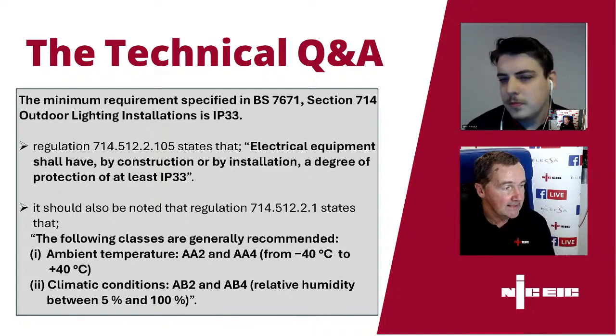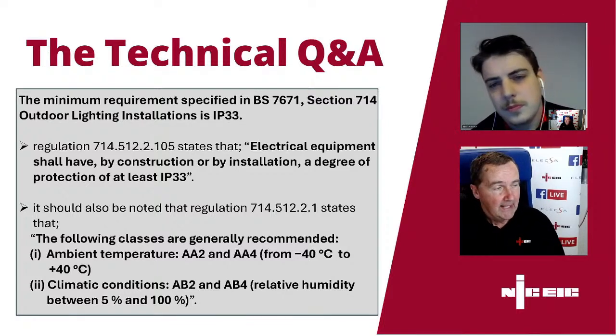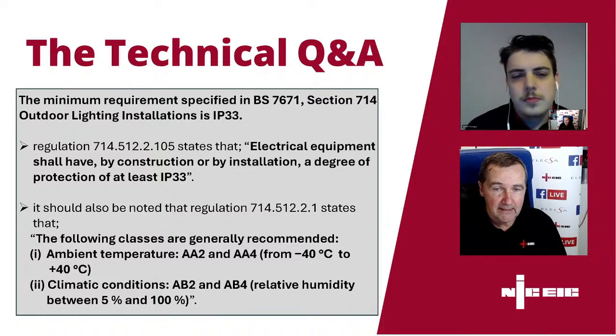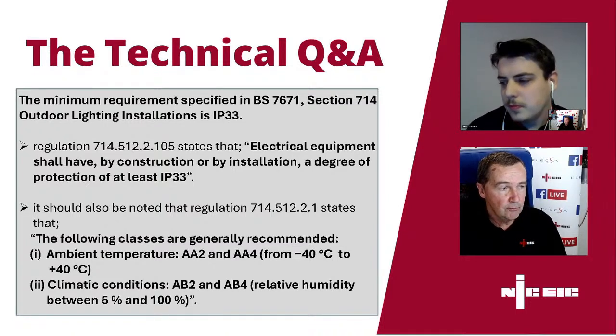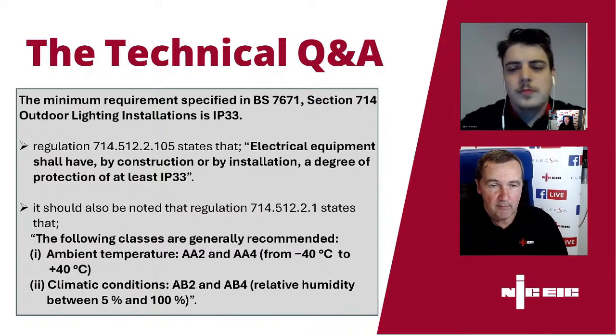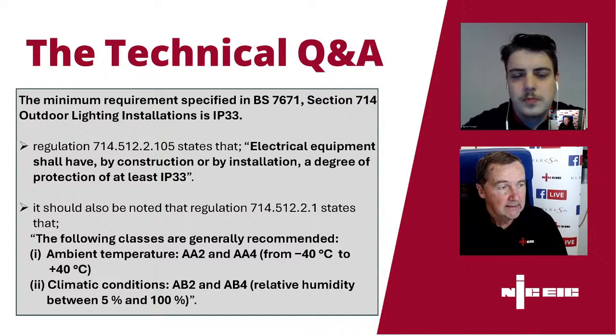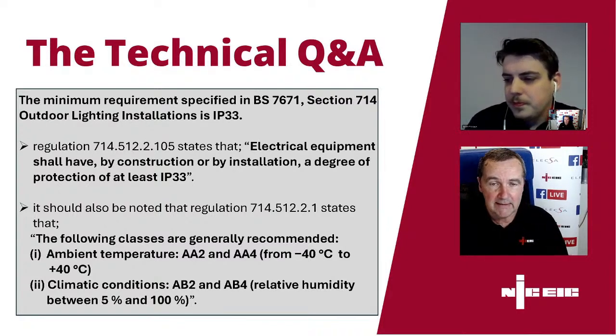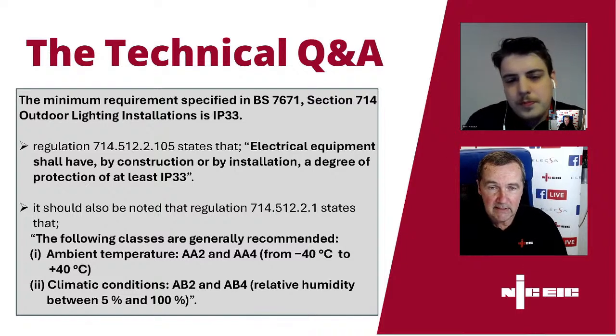What you need to consider in those situations is, at that intake position, bonding everything so that although you won't achieve the required disconnection of 5 seconds, for example, or maybe 1 second for a TT, eventually your protective device will operate, because if that fault current is large enough, it just won't operate in time to achieve your maximum disconnection times for protection against electric shock.